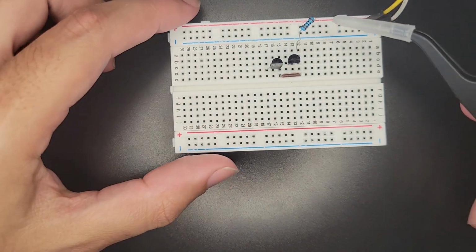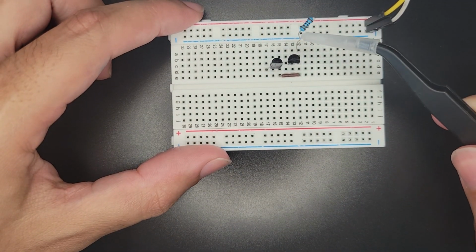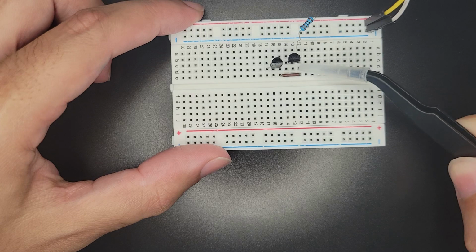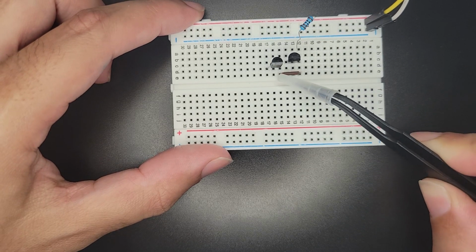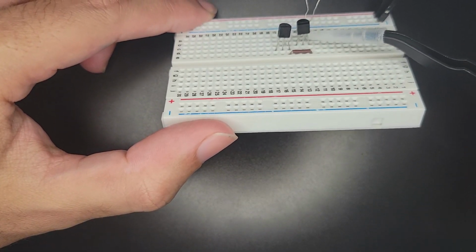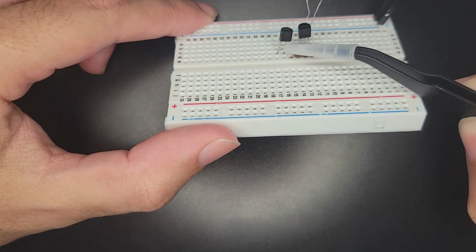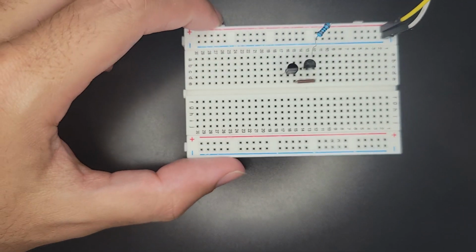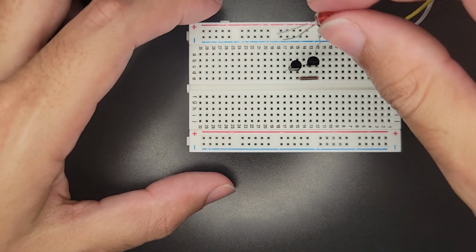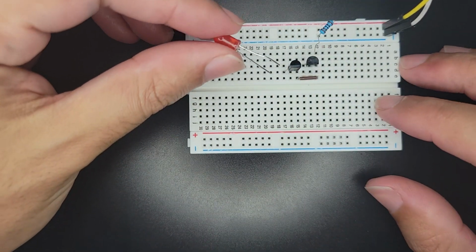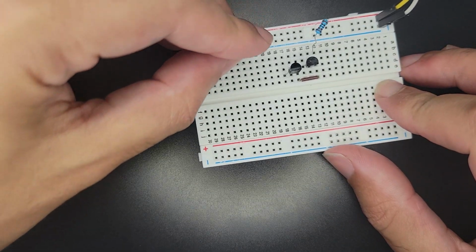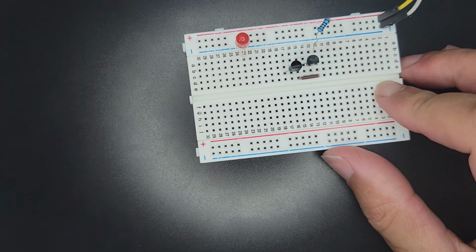So they're both receiving power from the resistor, right? So the power comes in through the resistor, goes up transistor A's collector, but it also continues down across the brown wire into transistor B's collector. So both of these should be collecting current together, and they're waiting for their base to be activated to allow the current to flow outwards. So what we need is something to show us the output. So I'm going to use our trusty red LED, and I'm going to move it way down here, and I'm going to stick him straight into the ground and on line 23. So that's our output.